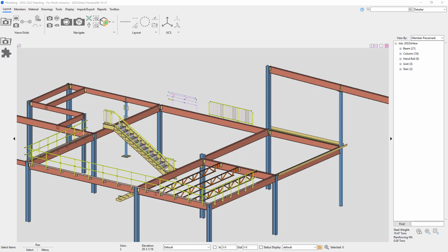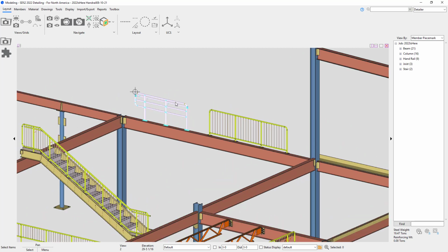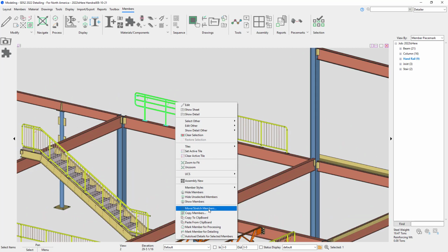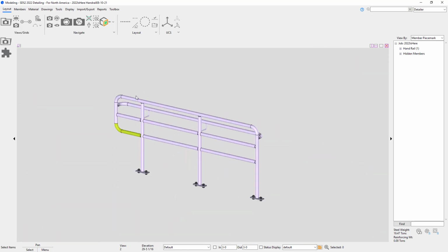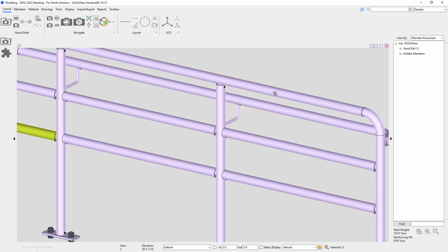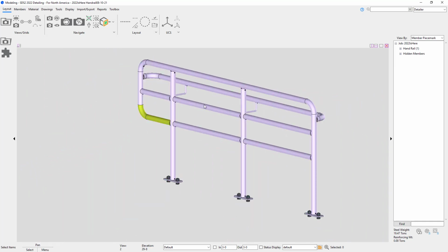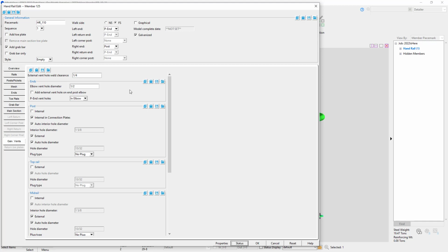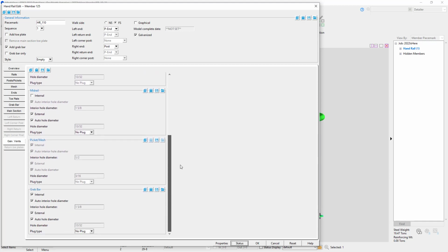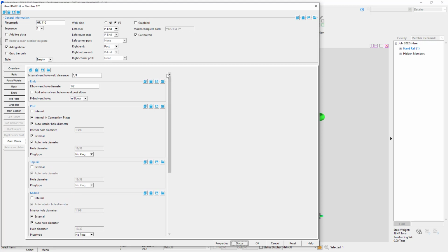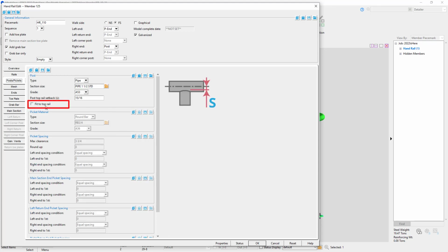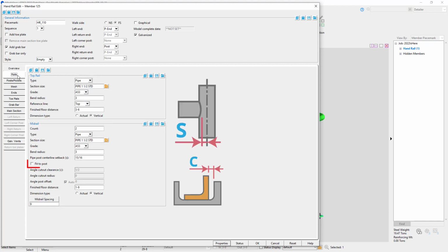We'll first cover handrail, and the first option there I will cover is the galv vent options. So you can now control the diameter of the internal vent holes. I can also do that for my top rail, mid rail, posts, pickets, and grab bar. We added in scroll bars to make it easier to see and navigate all of your options. I am going to show in the posts and pickets, fit to top is unchecked. And also in my rails, the fit to post is unchecked.